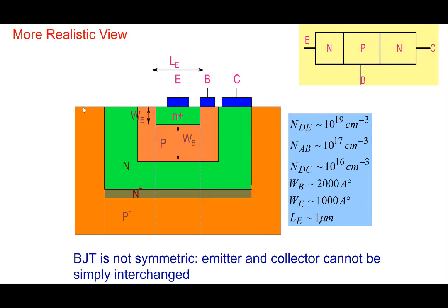you make all the transistors in integrated circuits on a crystalline piece of silicon, a silicon wafer here. So let's say you have a silicon wafer which is P-type doped. And then what you do is in this particular wafer here, you diffuse N-type impurity and then P-type impurity and then a heavy impurity N plus here. And so this is the N-type, this is the P-type, and then this has become N-type. And there is an N plus region here to provide a low resistance path to the contacts here.